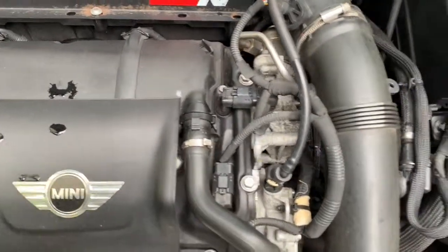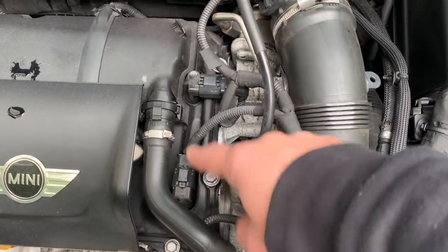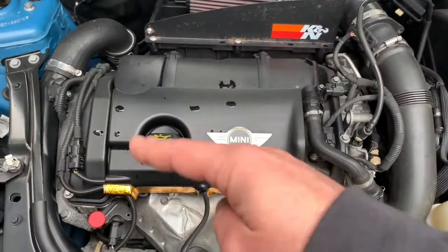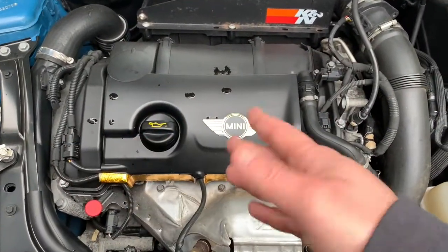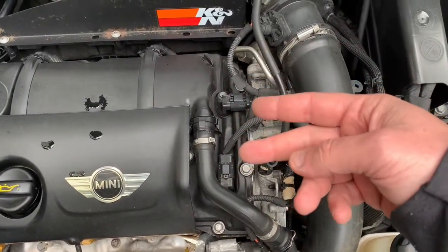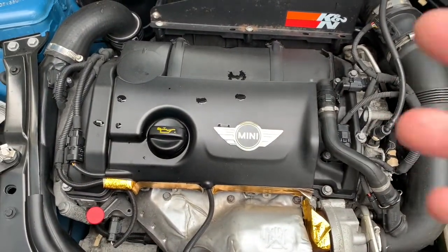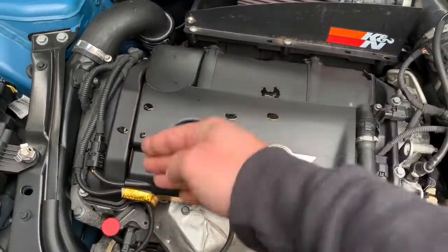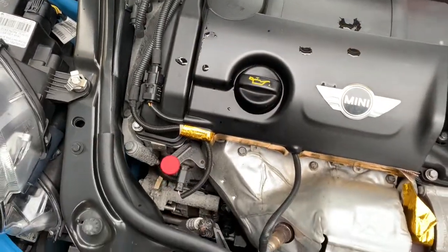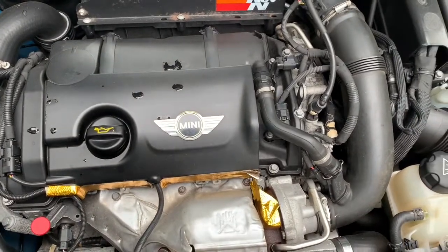Okay, there are 2 camshaft sensors. There's one here and there's one here. So this car both controls the intake and the exhaust camshafts as variable, and then we have 2 sensors to monitor where those camshafts are positioned in their phases. If there's a fault, either with oil pressure or valve timing, the timing chain in here is not known to be very good quality, unfortunately. Anyway, it would set a check engine light. Yeah, so that's where that stuff is.